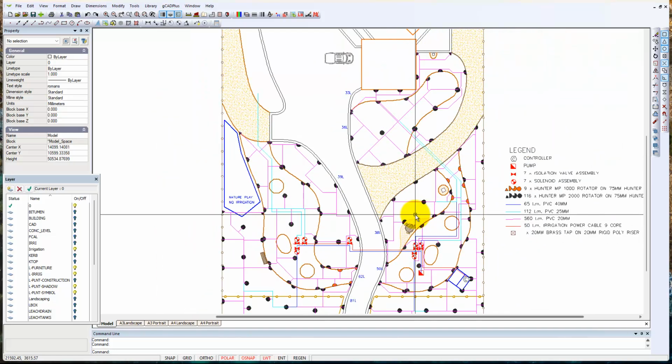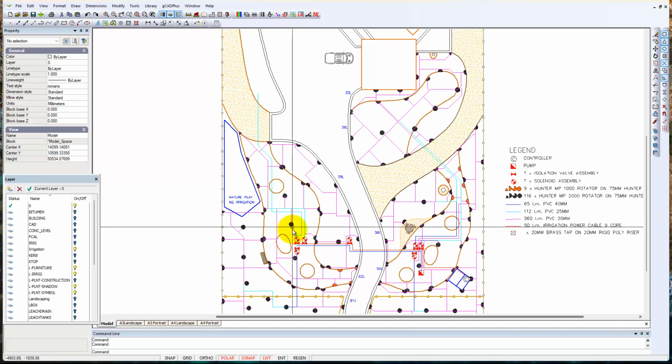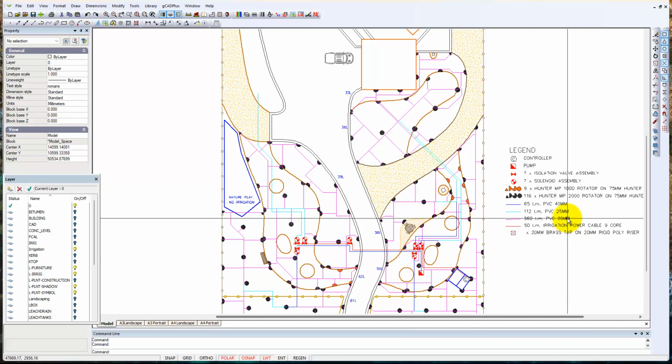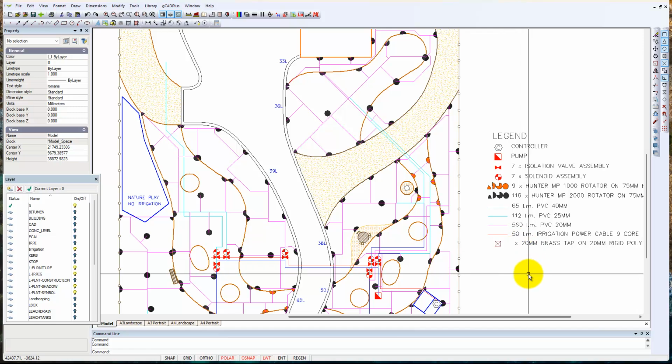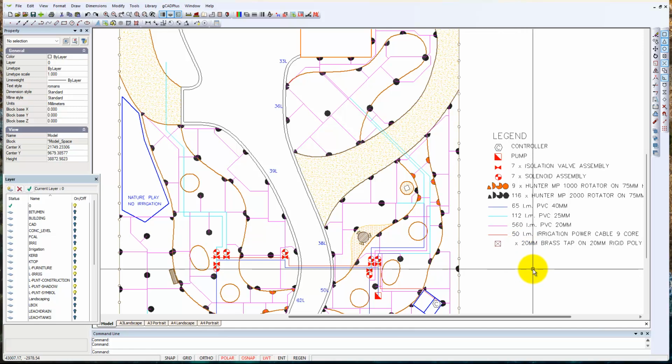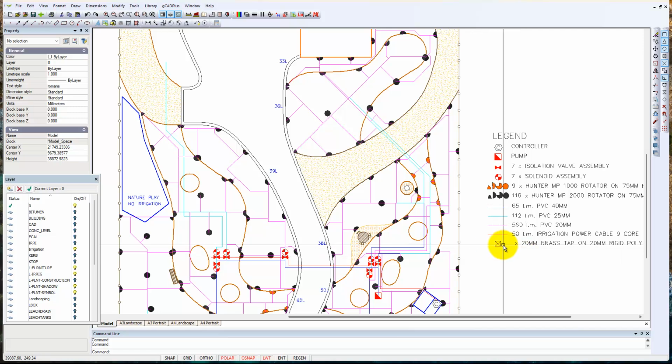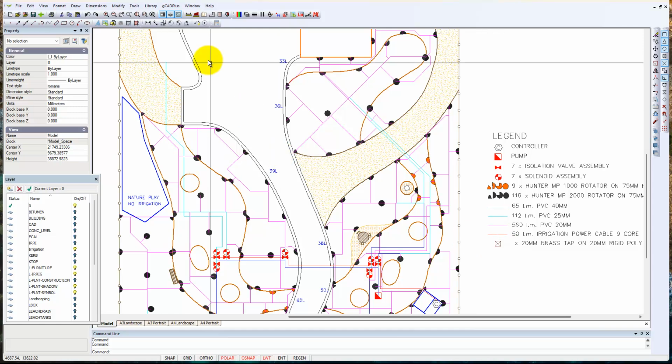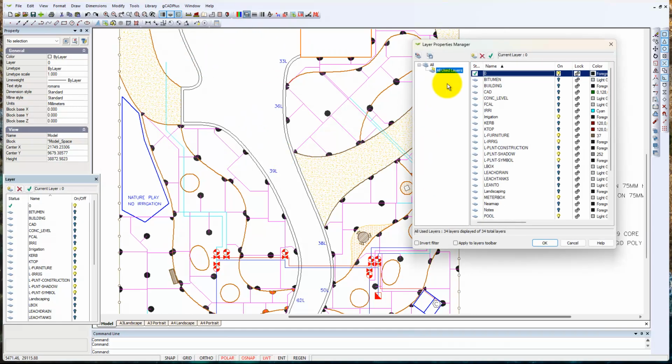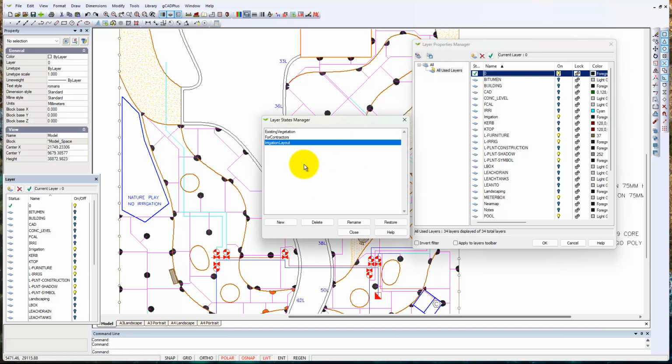We're now looking at the irrigation layer, very nicely done, irrigating all the grassed areas and what will become new planting areas. And there's a very detailed legend for rotators for irrigation, for PVC at different thicknesses and so on. So all the information there is available for a contractor to come in to install a sophisticated irrigation system based on this design.